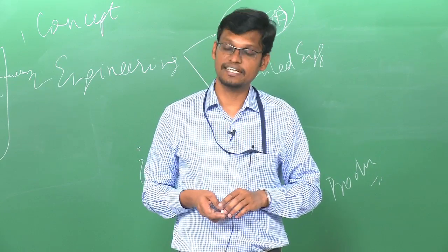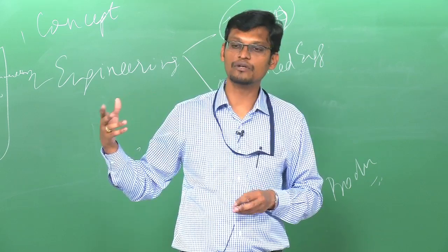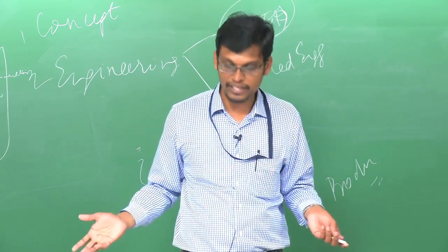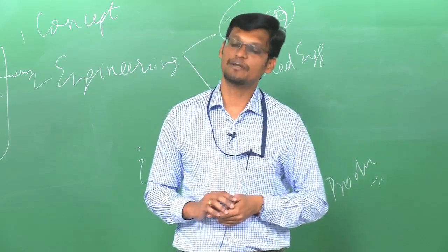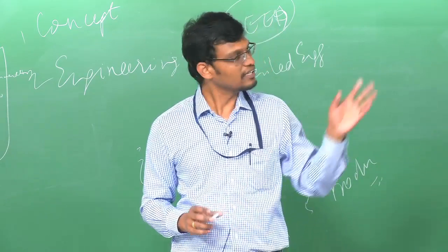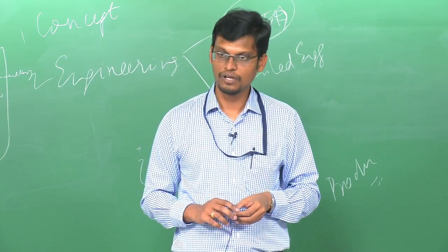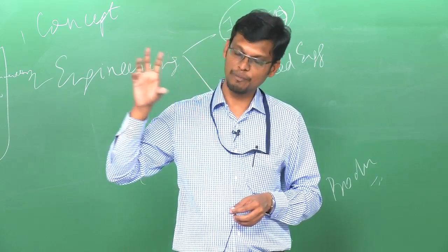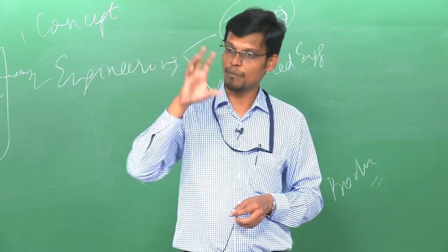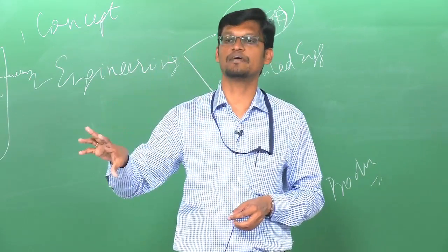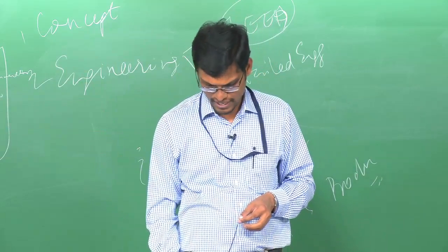And severity class: assuming the failure happens, what happened? Is it going to injure somebody, is it going to kill somebody, is it going to result in a fire? All that is what happens in a failure modes and effects analysis. Now, there are multiple techniques available. In fact, there is an EN standard also. It depends upon which type of equipment you want to use this technique for. Accordingly, you can customize your probability table and your severity table; the whole point of this is that it can be customized.